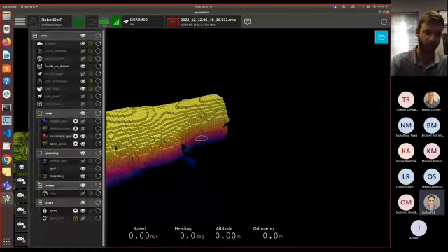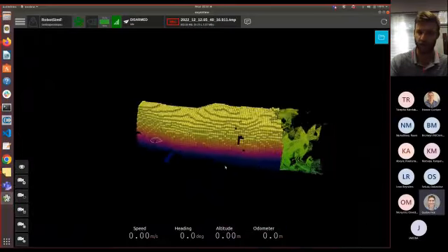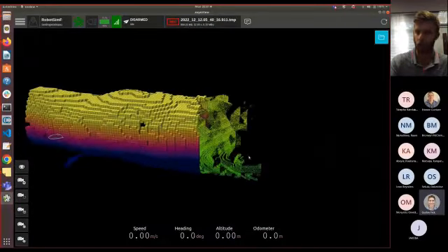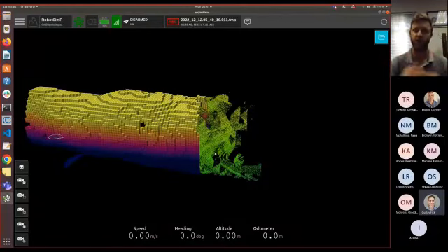You might ask, well Joel, why are there points at the front of this point cloud that aren't cubes, because this is a wall? Well, because the robot's still far away from this specific area, it doesn't have enough points yet to figure out that it's an obstacle. Once it starts getting closer to an area, it'll fill in those points and make it an obstacle.